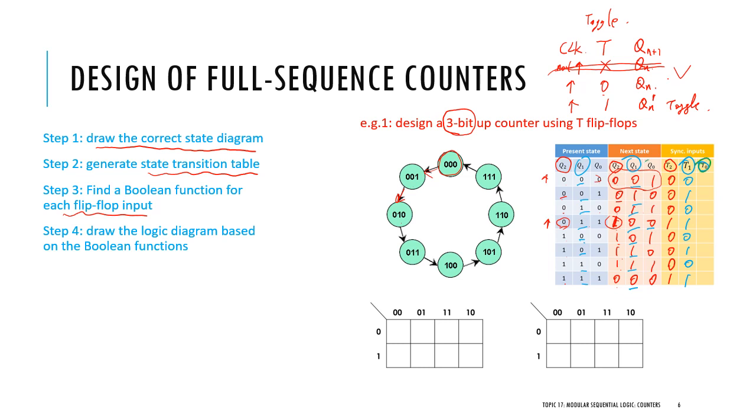So we use green here. So 0, 1, toggle. 1, 0, toggle. 0, 1, toggle. 1, 0, toggle. Actually, you can tell for T0, it's always in toggle state, right? 1, 1. Oh, no, actually, for the last two, it's not. No change. Okay, so now we have all the T values. Next step, find the Boolean function for those T values. So here, I think I missed one.